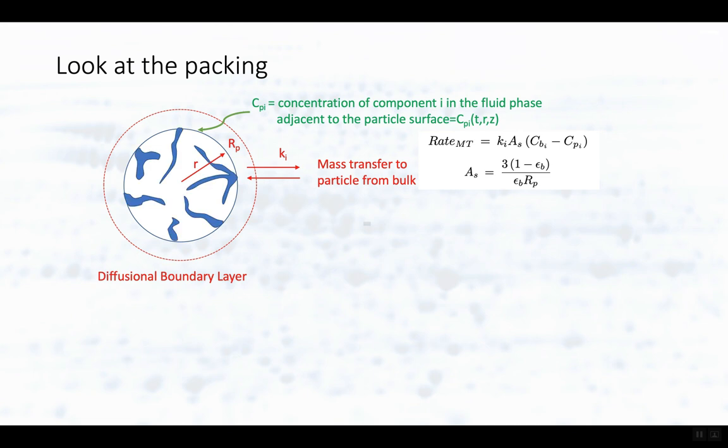Now, particles can also have porosity. Now, the porosity does not allow bulk flow through the particle. This is pores in the particle itself. Okay, so we do this because it increases the effective surface area for binding of materials to the particle. So very often chromatography particles are highly porous, and we have to now worry about diffusion in and out of the particle pores.